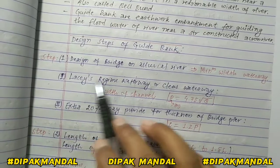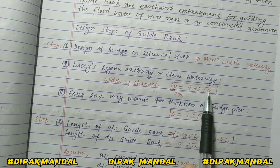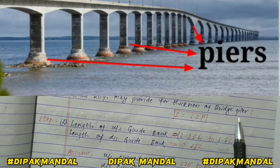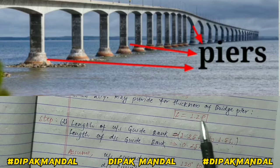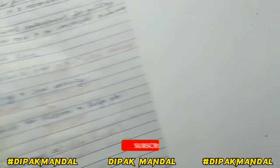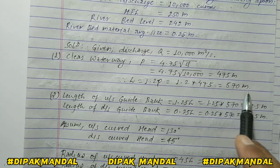You can see here we have to calculate the value of P using Lacey's theory. So P equal to 4.75 root under Q, and an extra 20% may be provided for the thickness of the bridge pier. You can see what the bridge pier is in the figure. For this we have to increase 20% extra. So L equal to 1.2 times P. That's why we take L equal to 1.2 times of P. So this value becomes 570 meter.